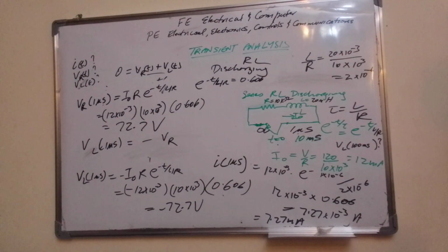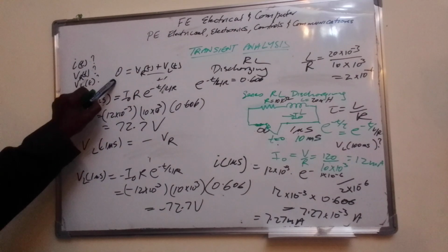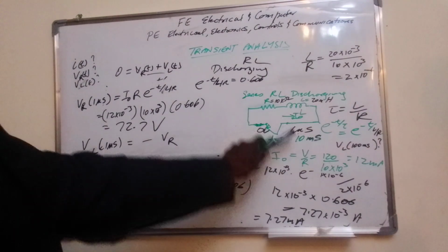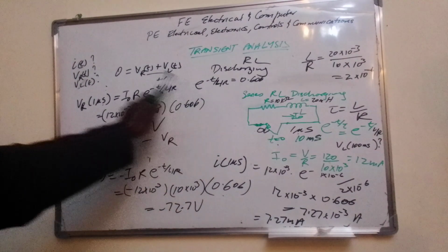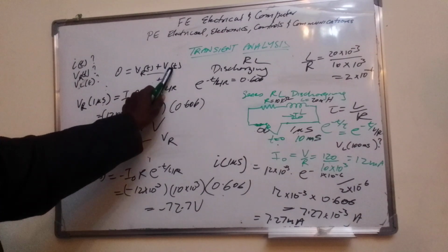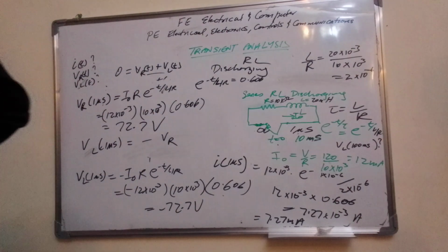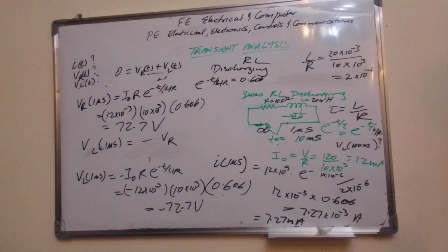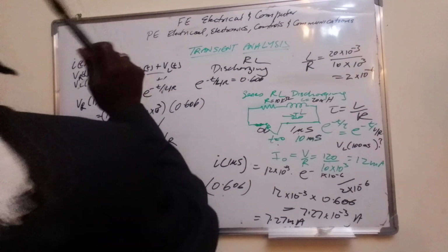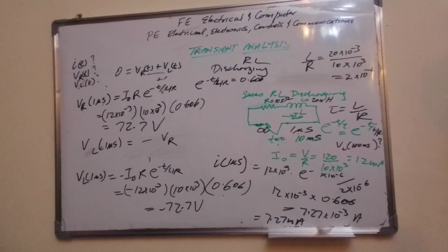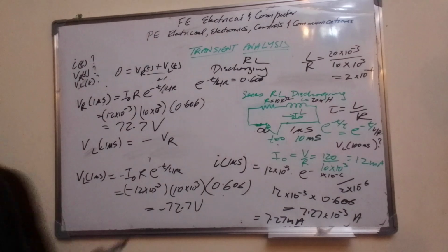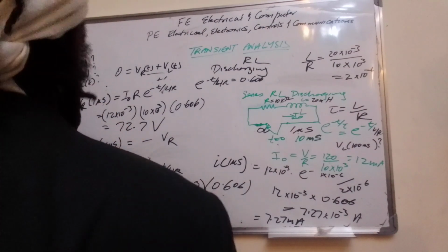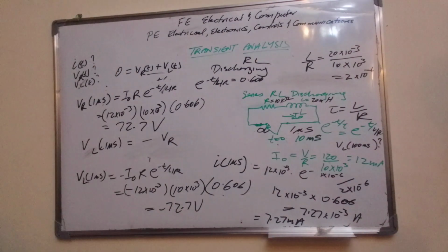Right, so remember that in the discharging situation there's no voltage source anymore. So everything is a balance between the inductor and the resistor voltages. In this case, the voltage will be leaving the inductor into the resistor and continuously discharging there. So whenever the inductor loses, the resistor will gain in that circumstance until the system totally discharges.